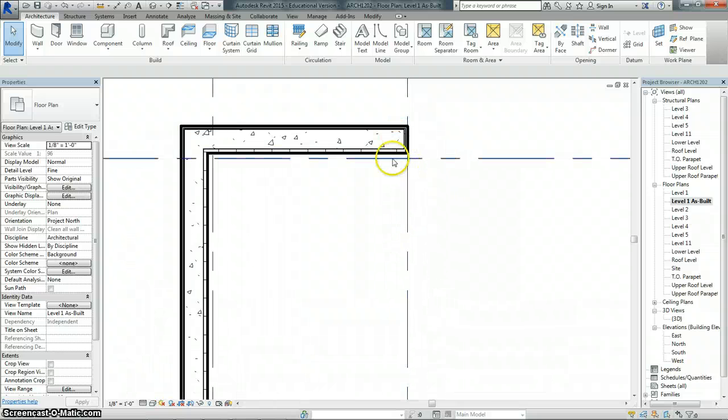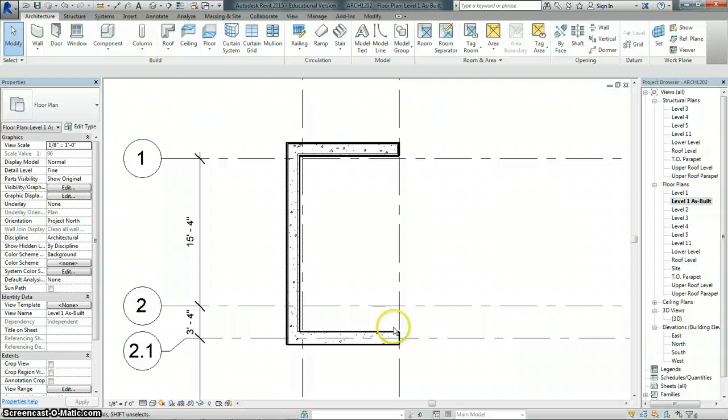Now the next wall we need to do is we need to bring the SW2 structural wall down here, so we need to build that wall, and that one will be the next one. And then this one's got a kind of unique condition because on the lower level it is a 16-inch wall, so it's centered, it comes all the way down, but on this level it's actually only 12 inches wide.